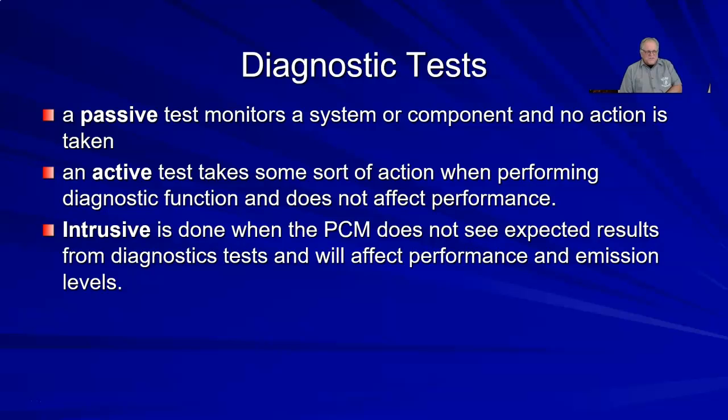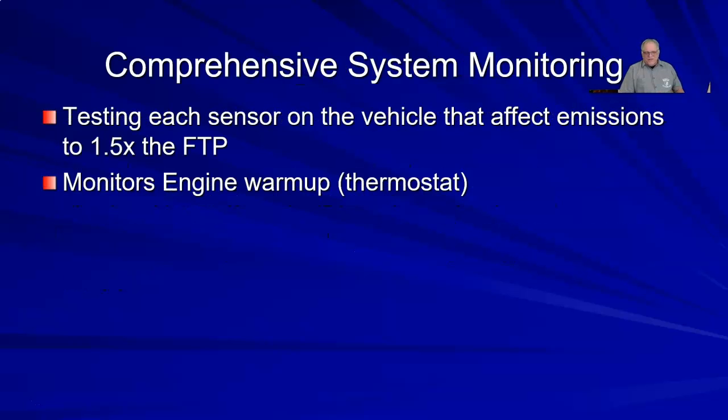On a rare occasion, there will be an intrusive test, and this again is where the diagnostic executive is going to take control of something, and it is possible, unlikely, but it is possible that the person driving the vehicle may feel this test. Any sensor on the vehicle that can affect emissions up to 1.5 times the federal test is going to be monitored in a comprehensive.